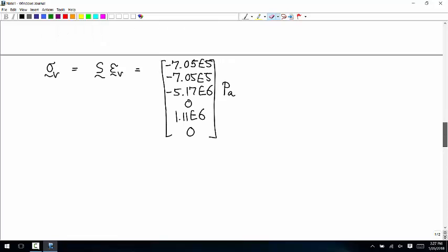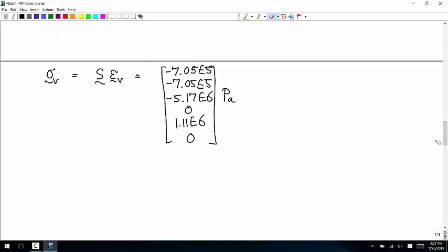And so then for part B, it asks you to express this in a rotated coordinate system. So first, right now we have the Voigt stress. To do any kind of coordinate system transformation, you have to represent that as a tensor. So just reformat this.